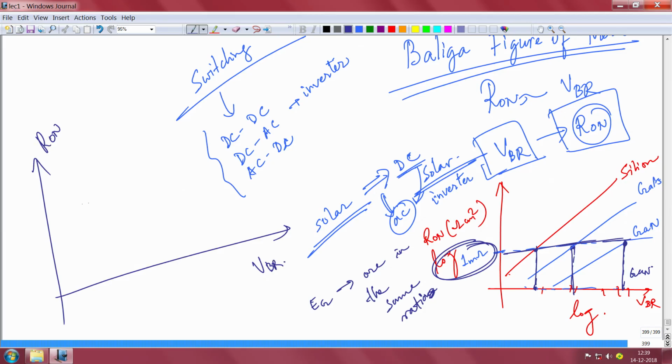What they will do is that if this is a silicon limit and this is your GaN limit, then they will do the scatter plot of where the things are. Here the gallium nitride things might be here. Okay, the gallium nitride has not quite reached the theoretical limit because the actual breakdown voltage is lower than the theoretical breakdown voltage. So, that is why it is here.